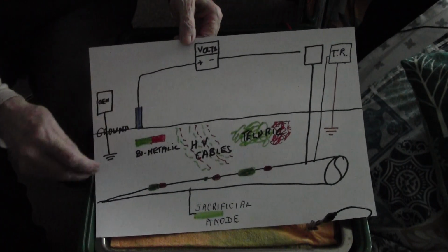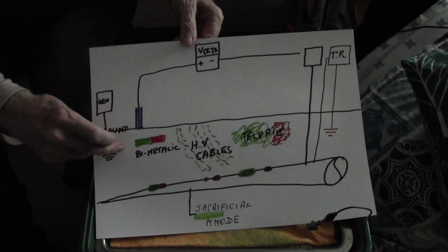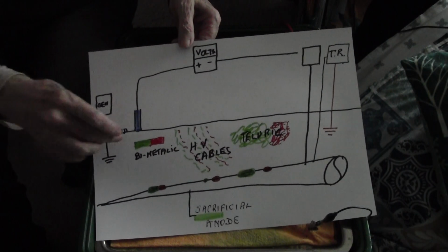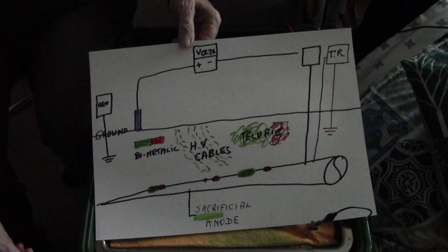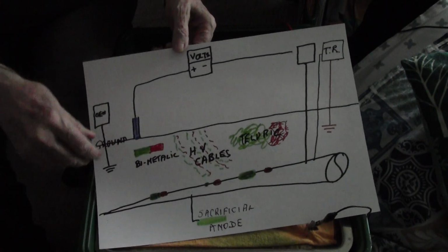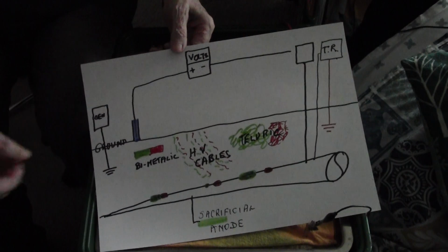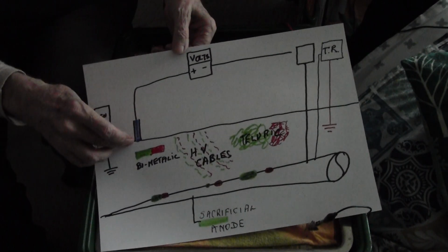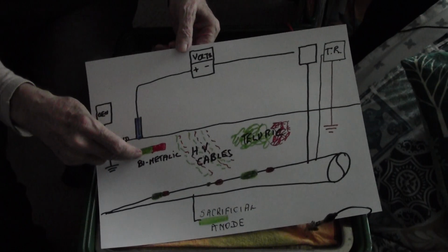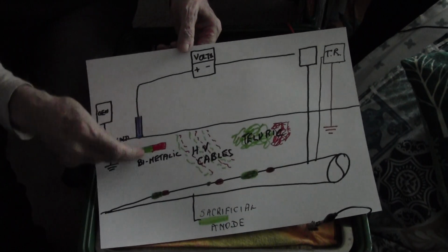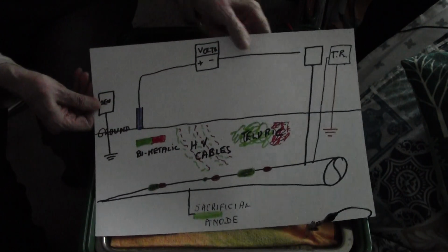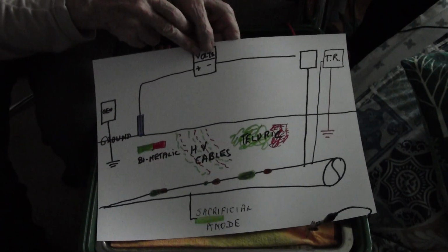If the electrode is put over the cathode of a bimetallic coupling, a lump of metal with copper and steel attached to each other, buried somewhere in the ground, you put your half cell over that. If you put it over the cathode, that will become part of the measuring circuit that is reflected on the voltmeter.